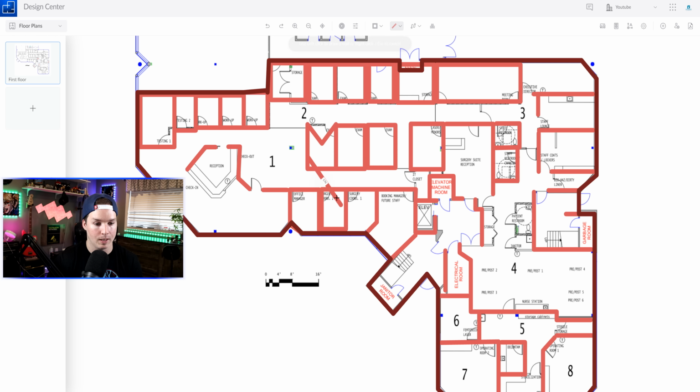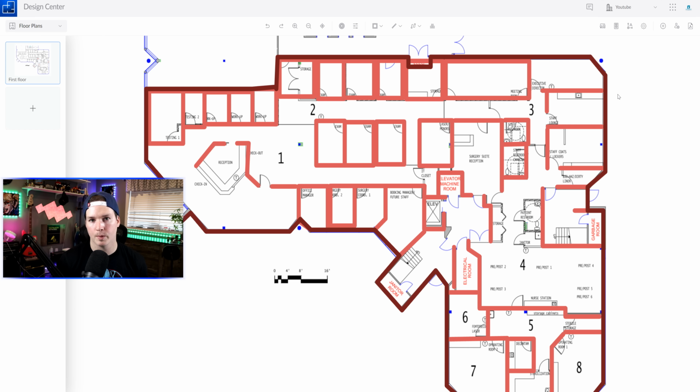So we'll put the corner, we'll do it inner, and then we could move this to scale whichever way we need to. Now that we have our walls put up, we need to start putting in devices, and they've made this list a little bit nicer. In the right-hand corner, we could click on this, and it's our device list.